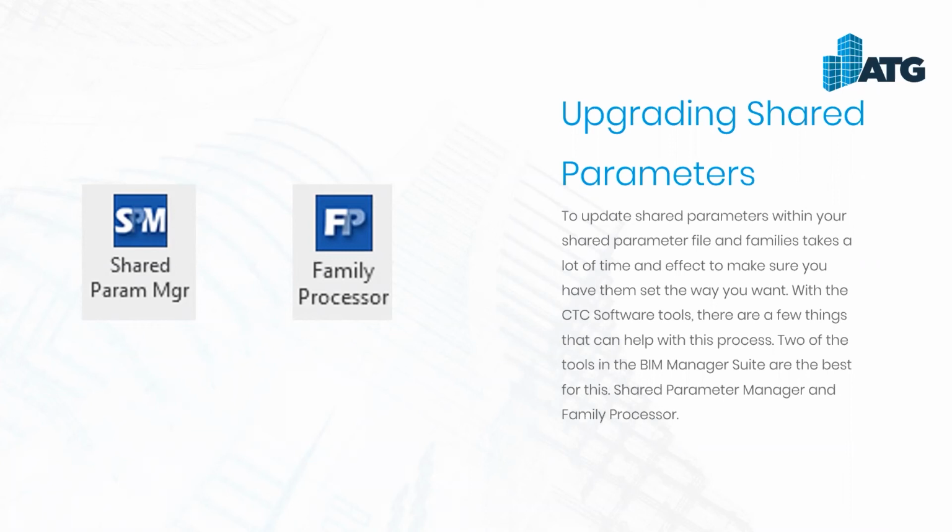Some clients have developed the workflow of inserting it into a family and then exporting it from that family back to the shared parameter or their other shared parameter file. That's just time consuming. That's not going to work. It just takes too much time. And then updating the families to now use that shared parameter is also very time consuming, because you have to go into the families, edit it, and swap it out. So that's where these tools come in.